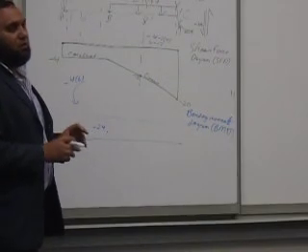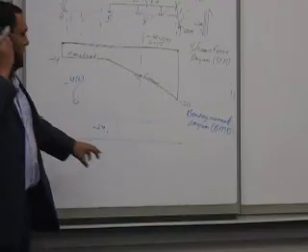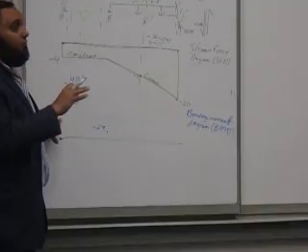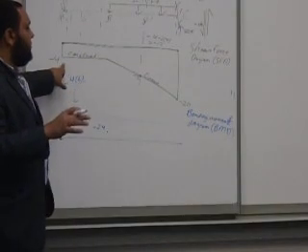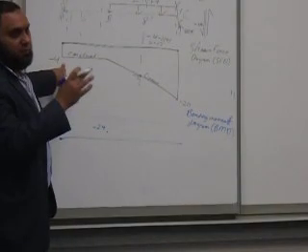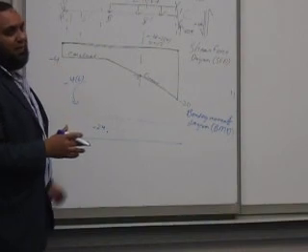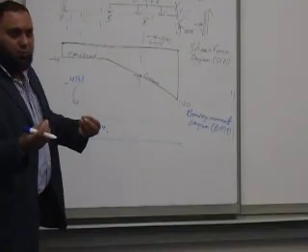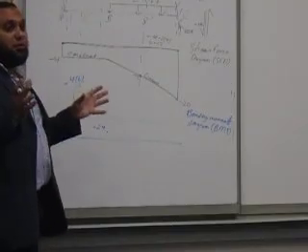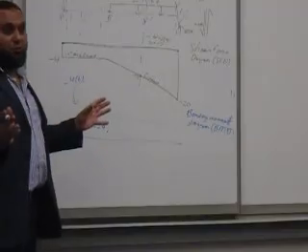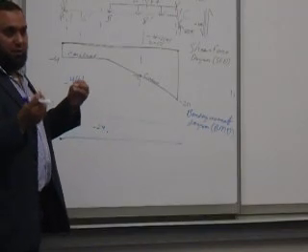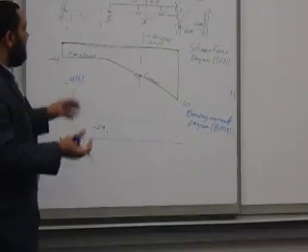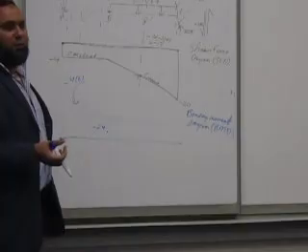Pay attention, girls, this is an important point. You notice something here. I'll draw the bending moment with the negative up. I know it seems very strange. In the shear force I drew the negative down and the positive up. Here I draw the bending moment with the negative up and the positive down. We'll come to the problem, be patient with me, I know. There are a lot of questions because I'm saying very weird stuff now. But be a little bit patient and you will see why. Let me even tell you: here, if you look at this arrow, where's the tail of the arrow?